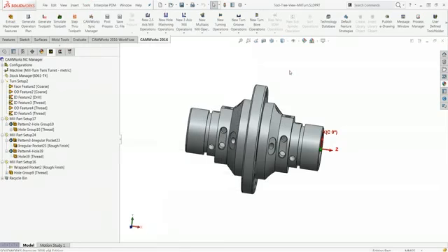What light rebuild does is basically rebuild any changes that have been made to your IFR features, so your interactively inserted features. If you added features in manually, those ones would be rebuilt if you just choose light rebuild. And if you want to regenerate or rebuild the features that were created by your extract machinable features, then you would use the full rebuild.